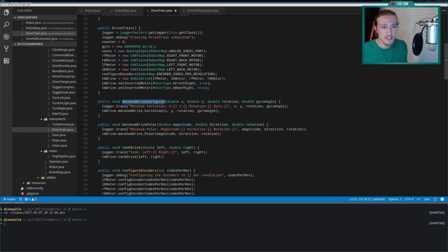If our wheel is 6 inches in diameter, that means we have 6 pi distance covered whenever we go forward 1024 pulses. That's how you can relate it to the real world, so that if in the real world I need to move 18 inches or so, roughly 18 inches, just doing math real quick, would put me at 1 revolution, and I could say stop after that. You can use that for a conversion. The encoders can also tell you speed, because you also have a relation in time there, so you can figure out how fast it's rotating as well.